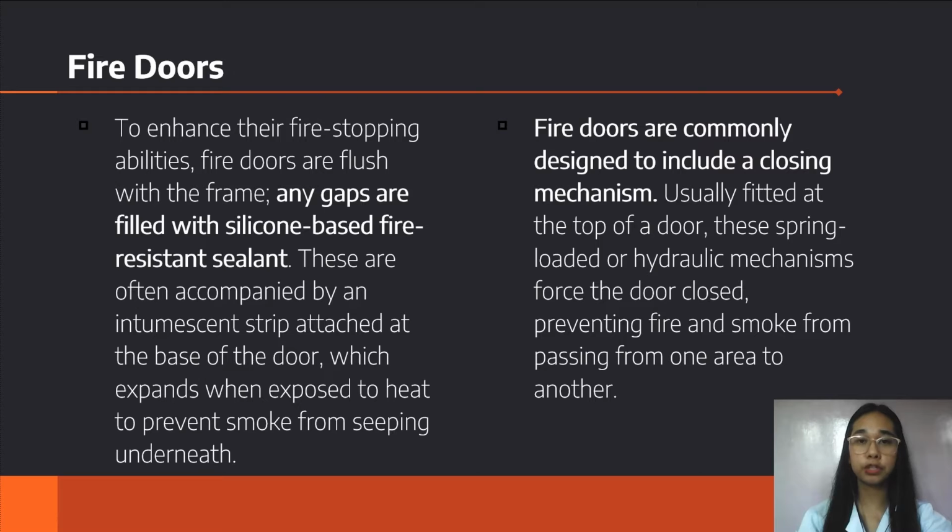It is worth mentioning that whilst many doors may contain some or all of these features, they may not necessarily be fire doors. To be called a fire door, a design must be certified by a manufacturer. Fire door certification is awarded once a door has passed various tests at an approved center, including a fire and stress simulation.